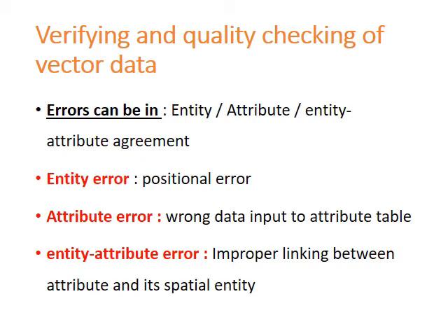Verifying and quality checking of the vector data that we have created. The raw digitized vector data always contains some errors and omissions that are not evident until logical connections are established. Vector data must be included with the topological information before it can be used for any analysis. Some errors might occur as a result of computational miscalculations and rounding error in the GIS package itself. Most of the database errors result from improper inputs. Even with the most meticulous map preparation procedures, the finest equipment and the best trained technicians, mistakes are likely to occur.